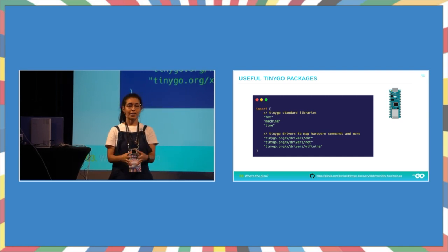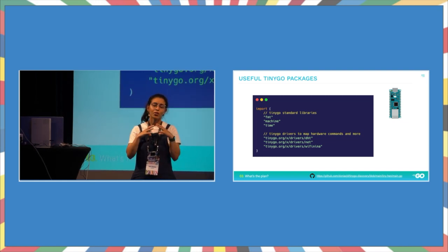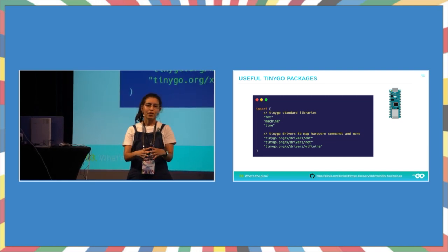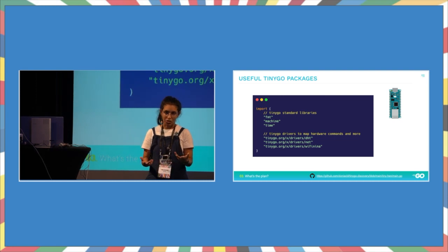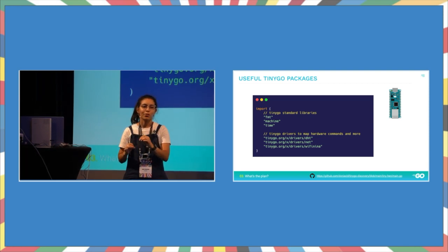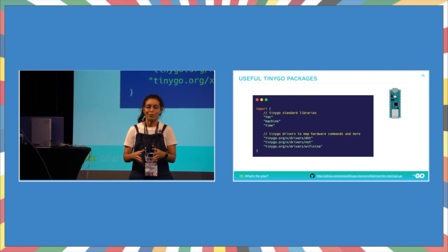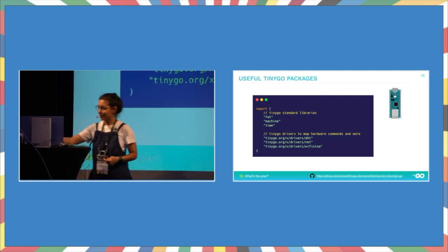I also use the TinyGo drivers, which are very useful here, because it's an interface layer that enables me to just call dht.Measure, for example, for my DHT, without manipulating bytes. Otherwise, I would have to send instruction 0x01 to ask for a measure. I don't want to do that. I'm a gopher. I want to have interfaces. That's the same for WiFiNINA, and also for net.